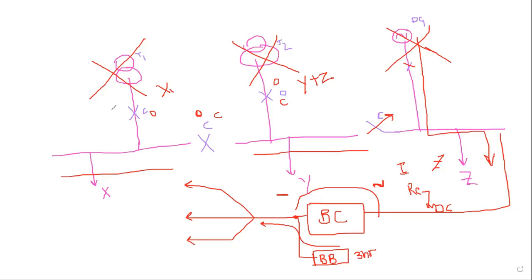If you see the scheme here, out of these 3 breakers, at any time only 2 will be in closed position. Either this 2, or this 2, or this 2. So how can you do this? You can implement soft logics, or generally, to save cost, we use a mechanical interlock here.